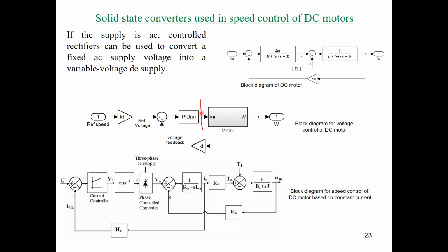However, when we try to control the voltage, we may get an output from the PID controller which may increase the input voltage of the machine. This may lead to increasing current. So it's very important to make current saturation or control the current. There is another modified control technique, which considers current control. Simply, we will have the same model of the machine, like the previous model.